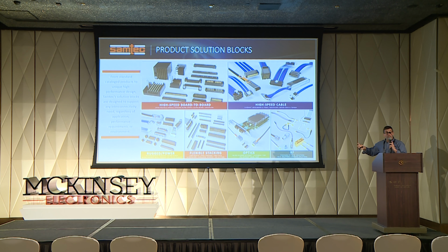Optics is a fairly new product group for us, about 8 years old now. That gets us to mid-board optical transceivers, very widely used in the EDA, emulation, test and measurement, and military aviation world. And finally, RF, very good for test points, our own 75 ohm BNC series, so in-house solutions, and also for test and SerDes testing.